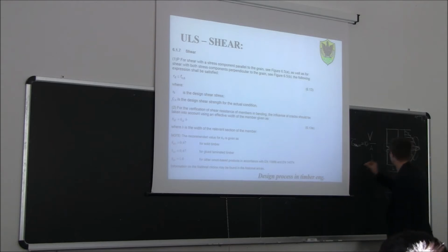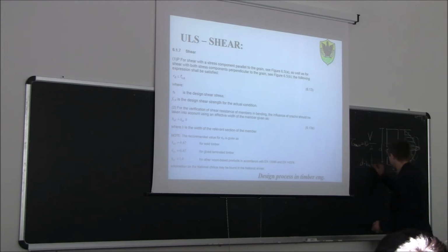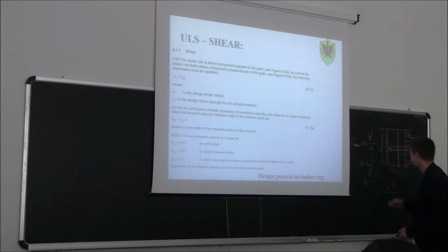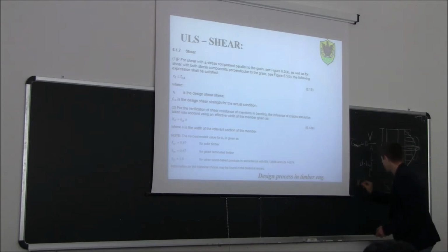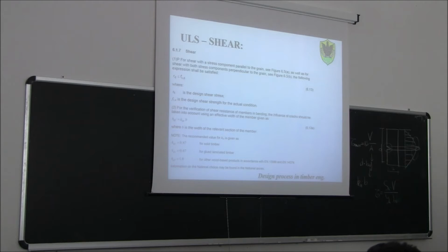Here we need to put d times b effective, where b effective is kcr times b. So we just introduced this coefficient of 2/3, so 0.67.